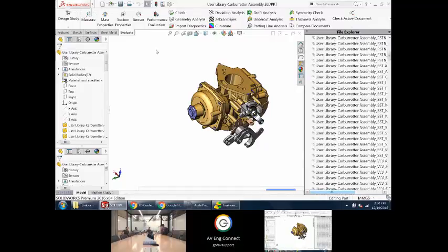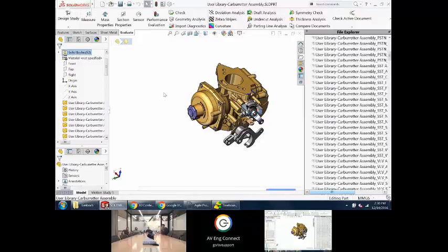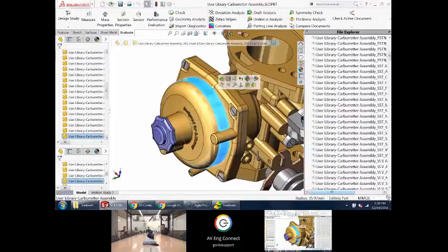So this is the one where you did the save as and then under geometry to save all parts, all components. So yeah, see, it's got 62 bodies here. Yeah. So every one of those was a part originally. It just saved every part as a body inside of this one single file. And the other option was like all exterior surfaces, and then you just get a list of surfaces. Right. It would be this face, this face, this face. And your feature manager should just be a list of faces.